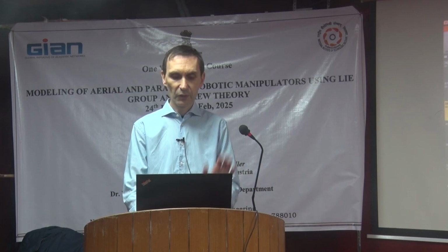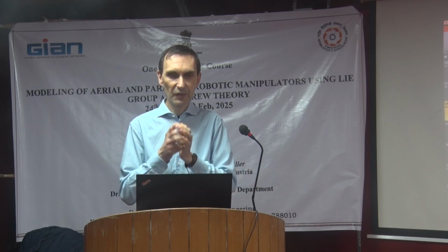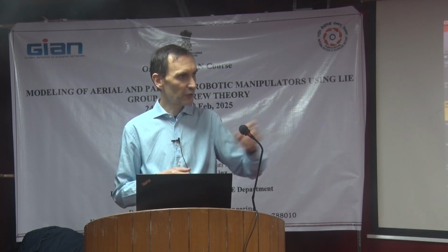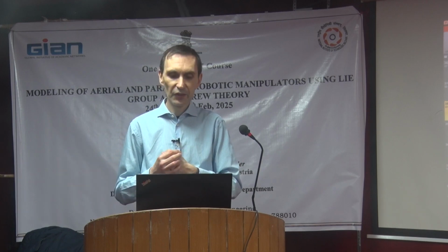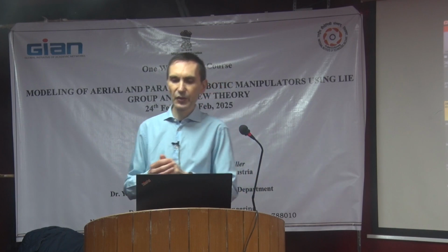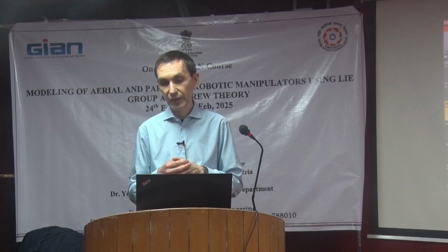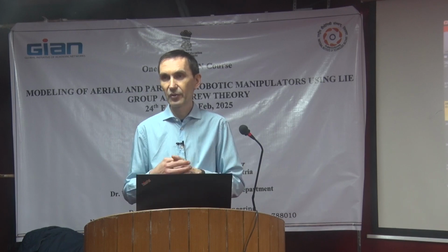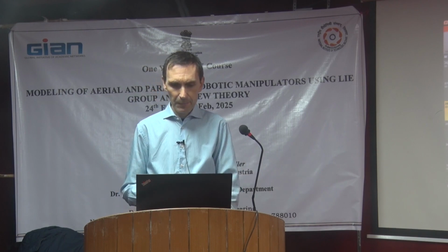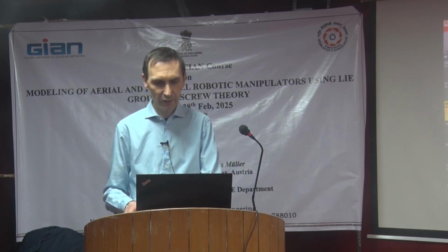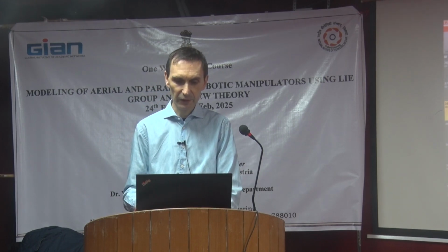I mean, the velocity. So what have you learned? Have you learned anything? You have seen the description using the product of exponential formula for open kinematic chain, using the exponentials and the screw coordinates for lower pair joints. I always use regular joints because they're easy to understand, but it works for any of these regular joints. Yeah, and there's a package for this, and this is a complete package with all functions, and it also goes to dynamics if you want to.